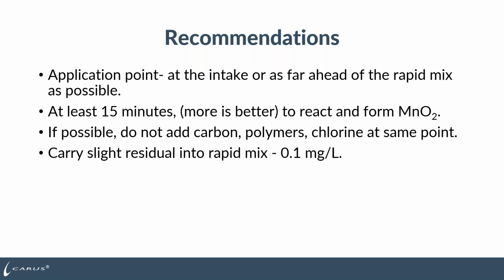Like I mentioned, the application point is typically the intake or as far ahead as the rapid mix as possible so you can get contact time, but you can take that contact time in the flocculators. For disinfection byproducts, we typically want to talk about having 15 minutes of contact time. More could be better depending on how reactive your water is, but you want at least a minimum of 15 minutes to get some reaction prior to adding all your other chemicals, or 15 minutes with the other chemicals added so that you still get them doing their benefit.